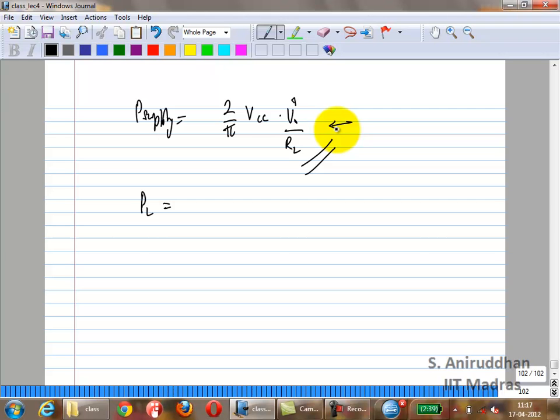Exactly. So one big difference is, if your signal amplitude is 0, power dissipated from the supply is 0. And that we already know, right? If you don't put in current, your current waveform is just going to be flat. There is no bias current then. So in other words, the power drawn from the supply is a function of VO hat. So what do you expect this to impact?